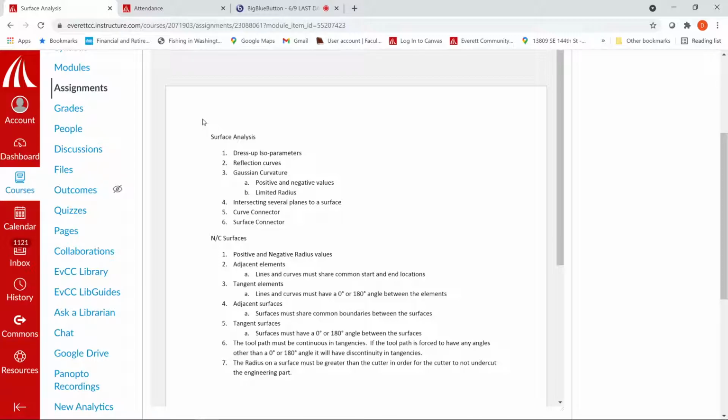that's going to be something that the other groups can work with, whether it be another engineering group designing from your part. So for example, if you're doing the OML surface or the MDS master dimension surface for a car or airplane or boat, let's say you're doing the hull and they're going to make ribs on the hull, well, everything's going to be based on that surface that you create. So they'll be using the surfaces you create to create the ribs on the hull of the boat.